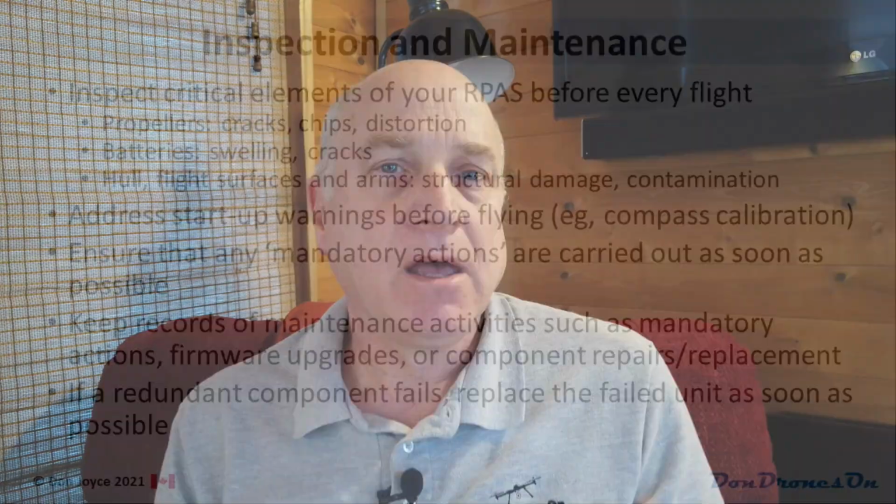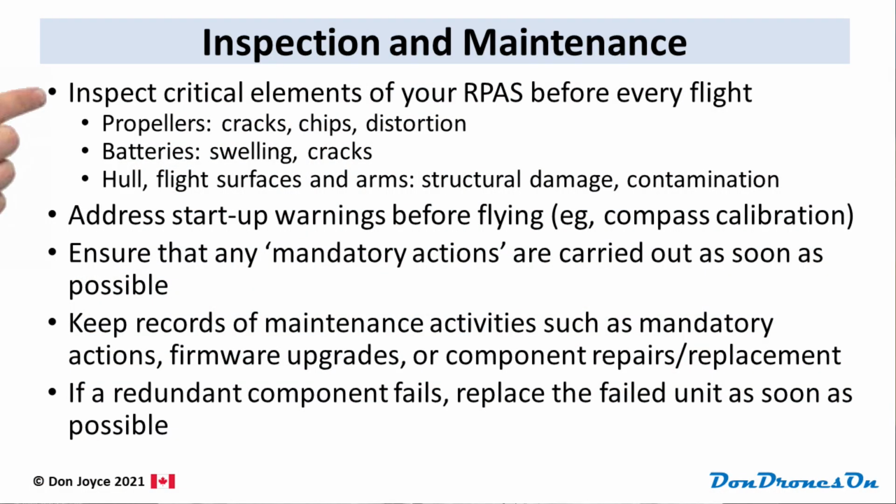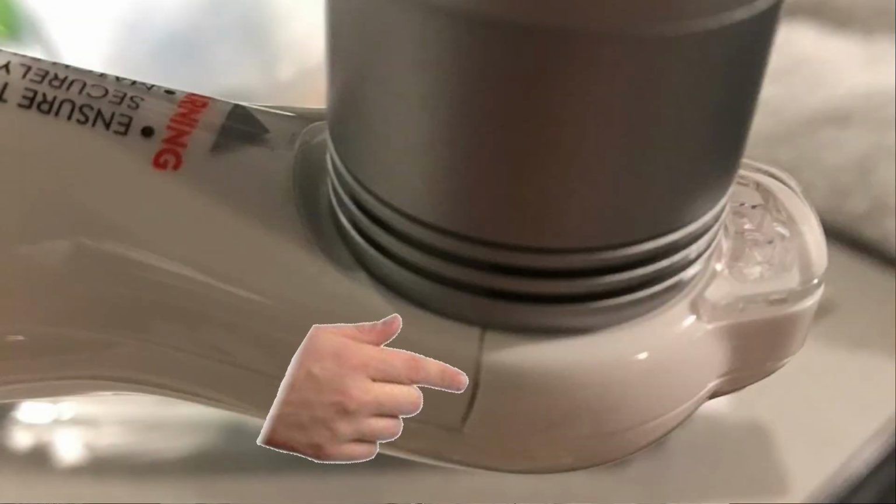Let's round this all off by discussing inspection and maintenance of all of these systems. Before and after every flight, you should inspect the critical elements of your RPAS, including at least the propellers, battery, hull, arms, and flight surfaces for cracks or other forms of damage.